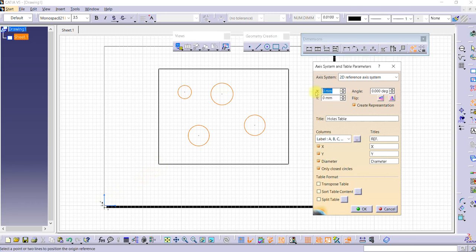So you just need to highlight this coordinate x, and then you click here. So now you can see the x and y axis already transferred to the new origin. So basically all the hole centers we calculate based on this new origin. Because this one is our plate, you need to have one origin to define as the reference. Then should be okay, just click OK.